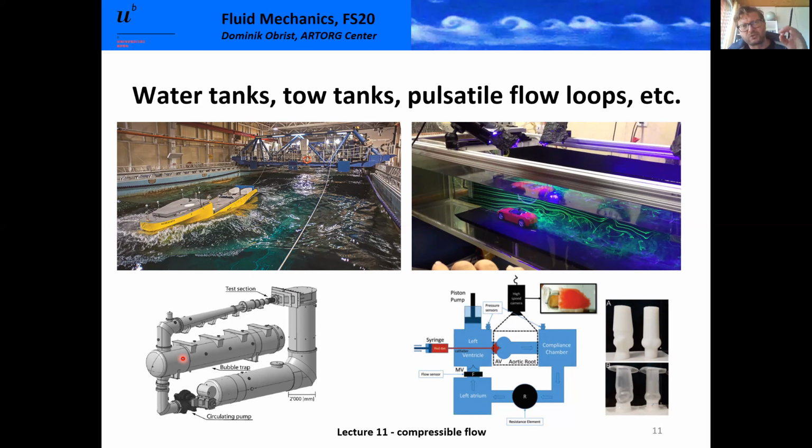If the pressure gets too low in a turbine, you get little steam bubbles. You have a phase change of the water, and when they collapse again, it creates a lot of local force that might actually destroy the vanes of the turbine. So this is a phenomenon that needs to be studied, and the test section, that's really why I'm showing this, is really, really small.